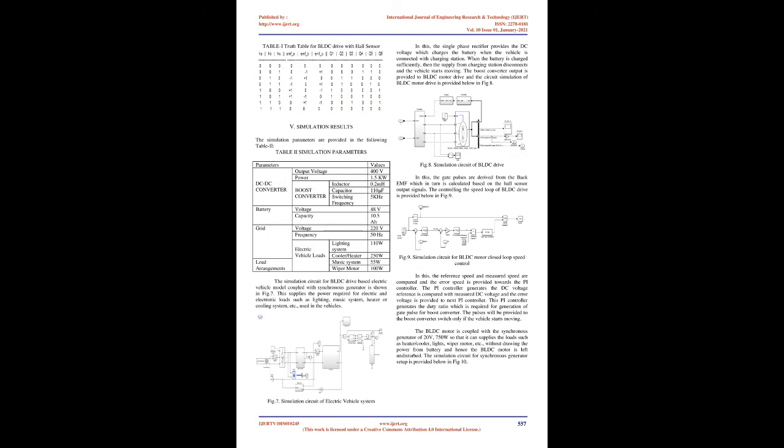4. Converter and motor controller. The strategy for controlling the BLDC motor associated with a boost converter involves two different parts: first, the control of the boost converter to vary the DC voltage, and next, the BLDC motor controller. A strategy of boost converter controller. In this, the controlled pulses are generated for the boost converter switch Q. The voltage tracking relation is used, which is in the voltage control loop, in order to control the output voltage of the boost converter, as shown in Figure 6.